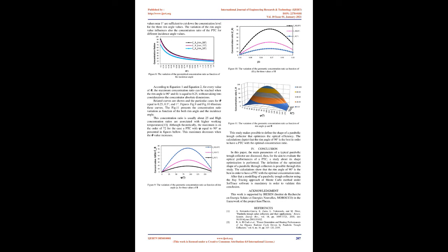Row shadowing. Shadowing between rows particularly occurs at extreme solar positions when the shadow cast by a collector closer to the sun obscures a portion of an adjacent collector. Fig. 6 presents the geometry associated with row shadowing. The shadowing efficiency is equal to the ratio of the non-shadowed aperture to the total aperture width, W, as shown in equation 6. End losses.